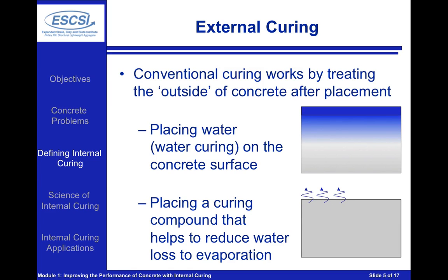And the idea of a curing compound is really to prevent the evaporation of water from the surface. So here what we're seeing is a film that will be formed across the surface, and that film is really to prevent or minimize the water that could be lost due to evaporation. Again, it's a little bit different than what we saw in the first case, where water was placed on the surface and that water would be absorbed by our concrete, because in the case of a curing compound, we're really just minimizing the loss of water from the system.